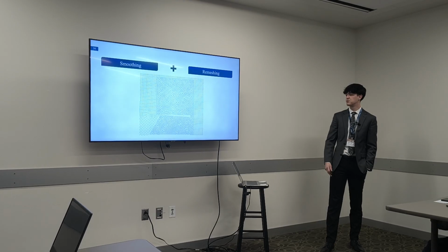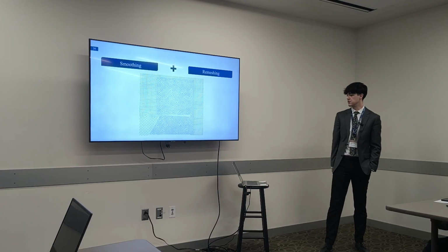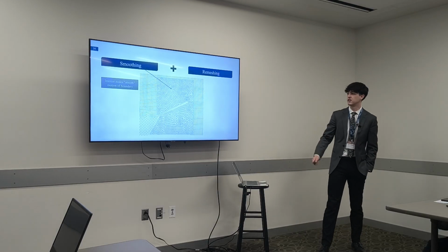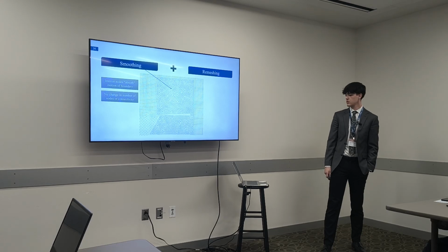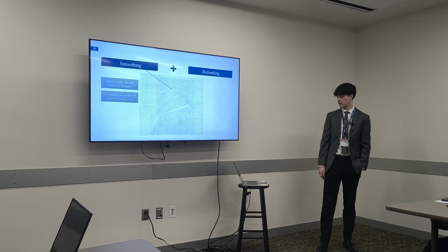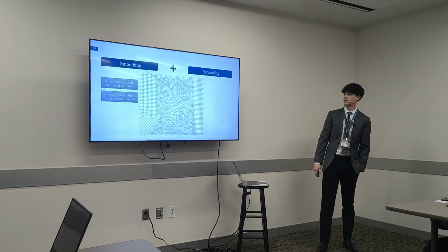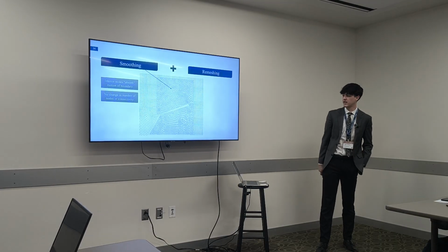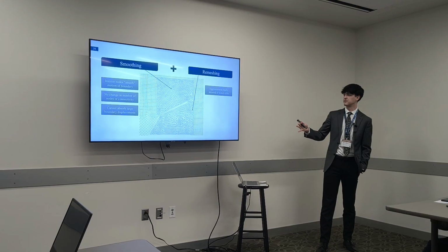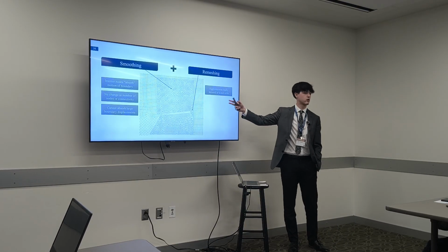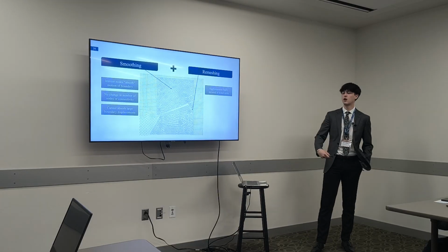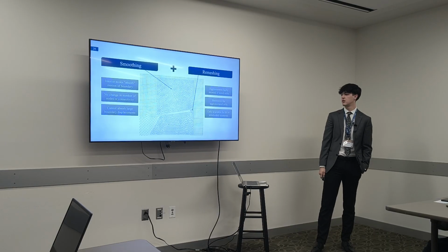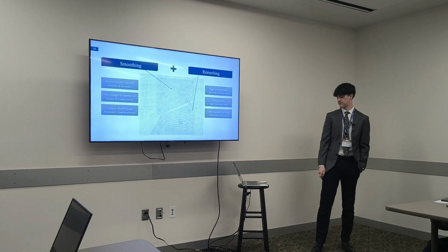So first we're going to be looking at smoothing and remeshing. We have a combination of these two, where smoothing first creates that absorption of the motion of that boundary, but there's no change in the number of nodes or connectivity. And so as you can see, those nodes continue to compress, but not agglomerate yet until we get into remeshing, and that's closer into our moving boundary there. It agglomerates badly skewed or sized cells and remeshes the agglomerated cells, but it's only available for tri or tetrahedral elements.